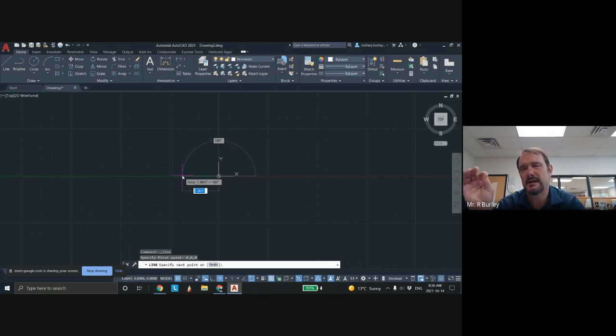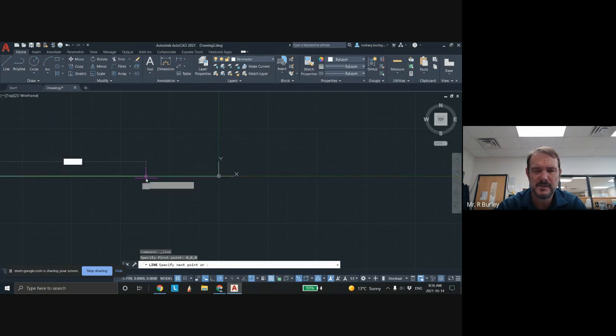What that's doing is locking it at X and Y axis and the Z axis at 0. Don't put a comma after the last 0, just hit enter. Okay, now we're going to walk to the left-hand side. And when we walk over to the left-hand side, we're going to go 850 millimeters. Enter. We're going to hit the escape key now.